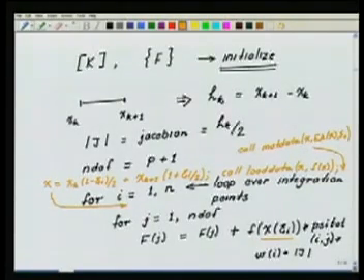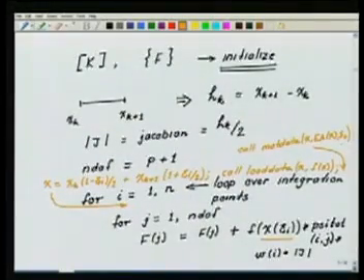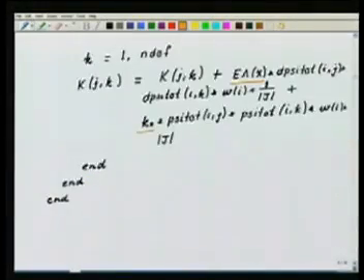So I will have to call for the particular x both the load data subprogram, which will return the value of the force F of x at this point, and also the material data subprogram, which will return the value of the EA and the K at this material point.